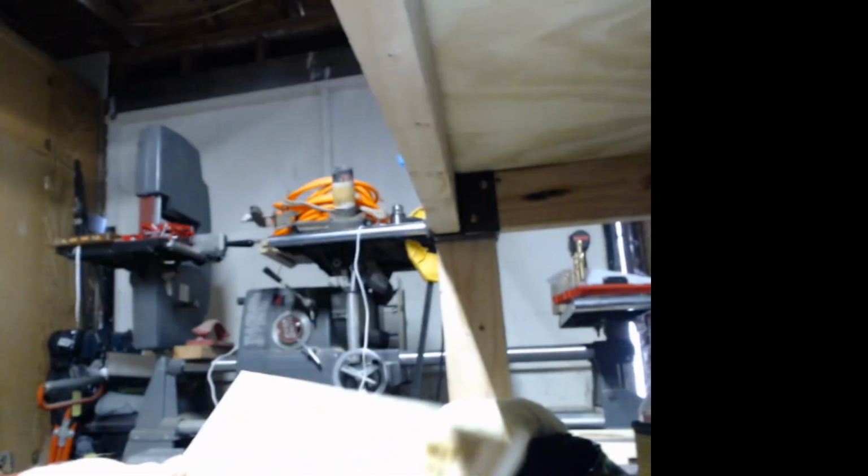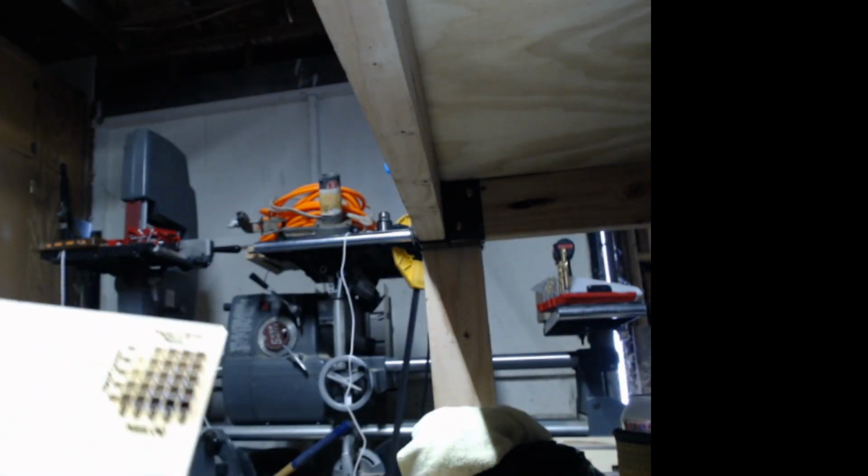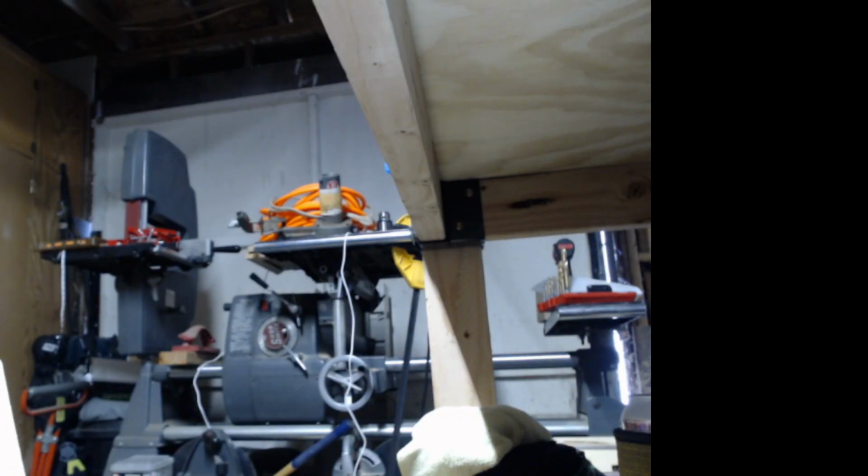So you can see it's a little bit of burning because I don't have my high powered air. You want high power air whenever you're cutting. In engraving you don't really want any air, with any laser. With cutting you want to have air turned on.